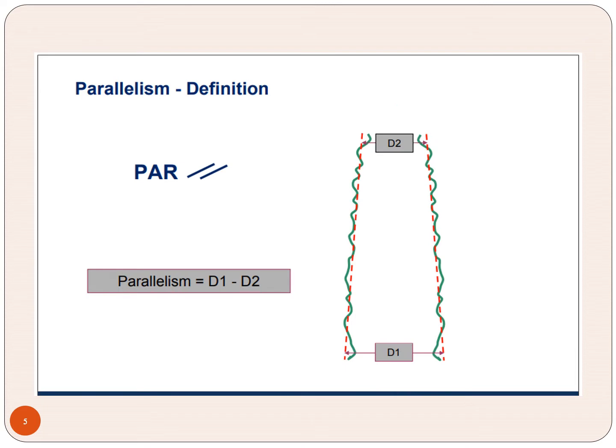If you are going to make gears with the manufacturing of gear teeth, by using the machine called gear hobber, or in a shaper also we can do it. Mostly we will be using the gear hobbing machine to generate the gear teeth. For making the cylinder itself, we have found the straightness and the parallelism have some minor error.